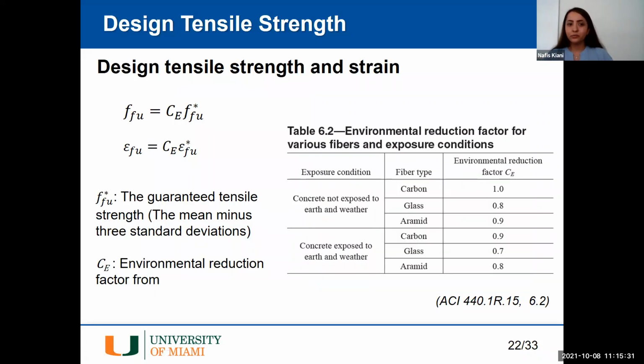Considering the different mechanical properties of the FRP bars, they have different responses in the case of design. For example, the design tensile strengths of the FRP bars given based on the ACI are reduced compared to steel by applying environmental reduction factors, which are very different for different types of FRP bars, and depend on the exposure of the reinforcement and the environment.